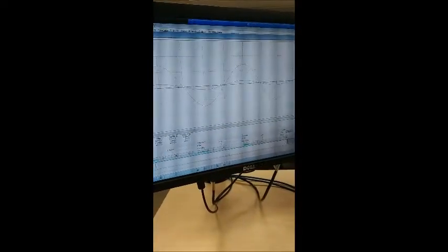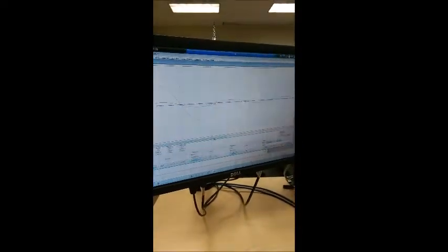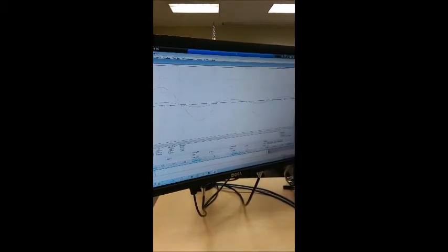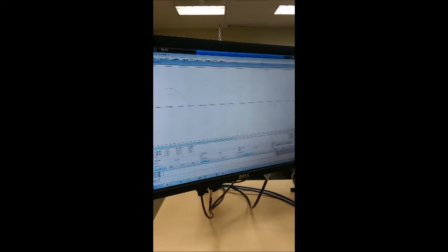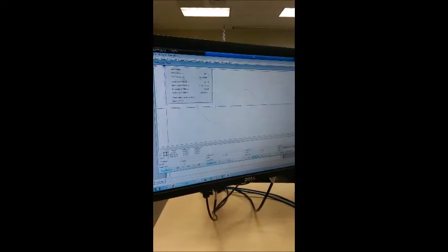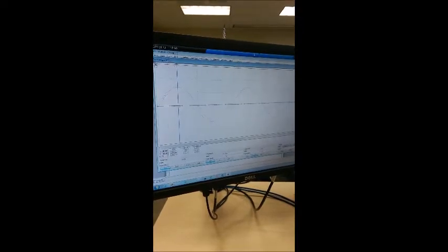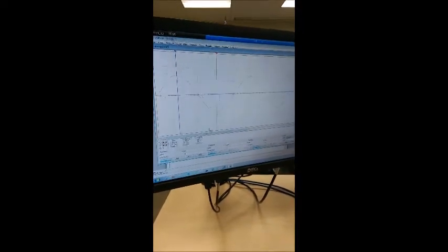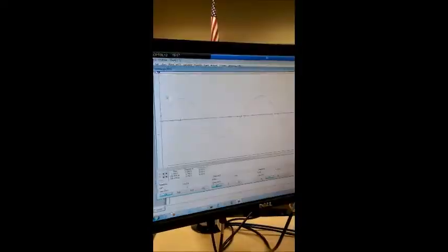First, we're going to measure the value of the power source. That's going to be channel A. So first, we want to hide channel B, and we're going to bring this line to Y max, and line number 1 to Y min. Okay, this value over here is the voltage peak to peak.